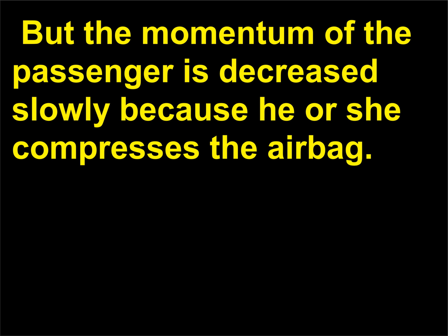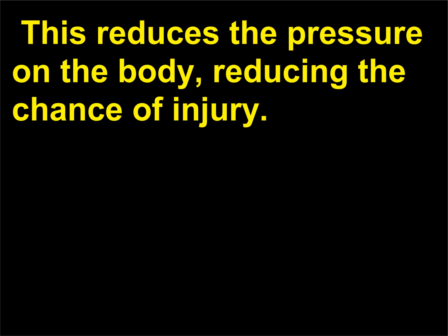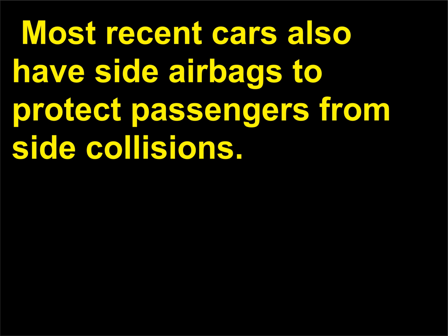But the momentum of the passenger is decreased slowly because he or she compresses the airbag. In addition, because the airbag has a large area, the force isn't concentrated, but spread out. This reduces the pressure on the body, reducing the chance of injury. Most recent cars also have side airbags to protect passengers from side collisions.